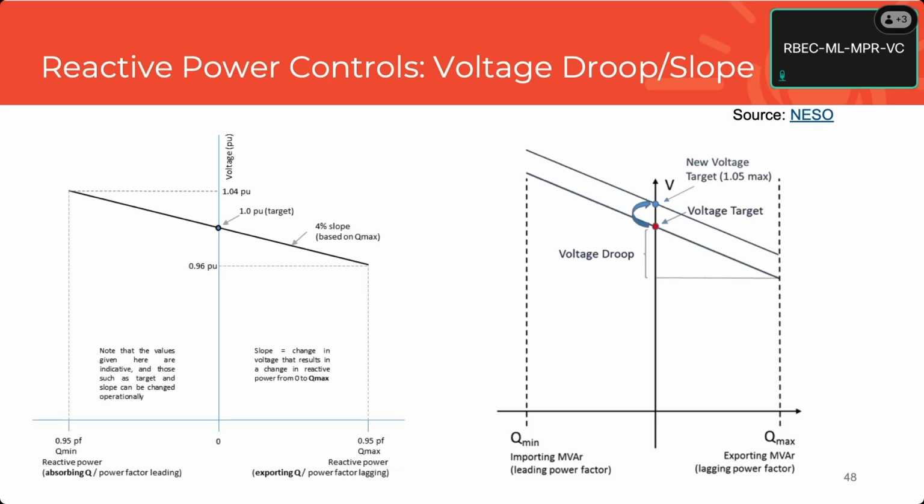But it's basically a defined way to ensure there's a single controlled operating point in response to an output. So it determines the degree of response, but it also will ensure that two plants next to each other will not be able to hunt. They only have one place they can be for a given voltage. Okay, if you set the droop too narrow, then you have problems with measurement and oversensitivity. They can start to fight again.